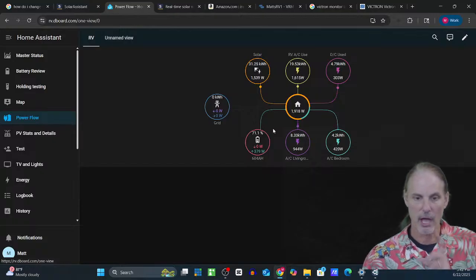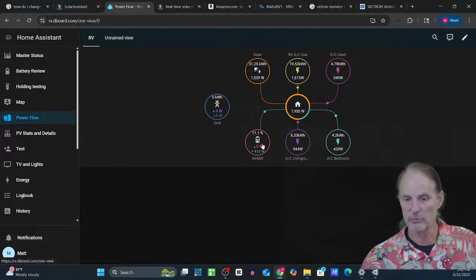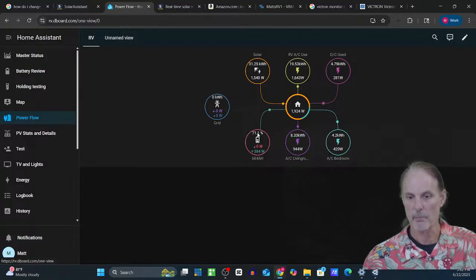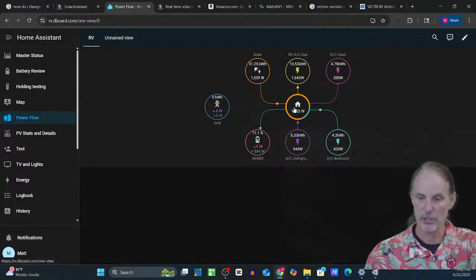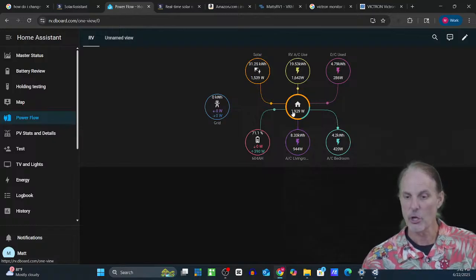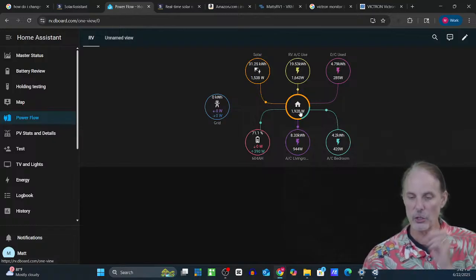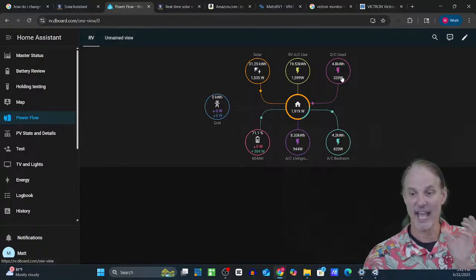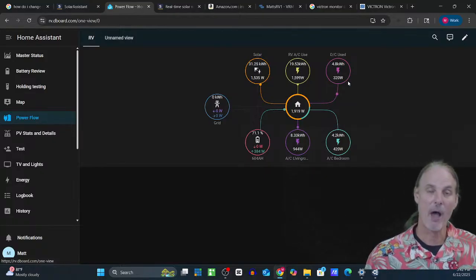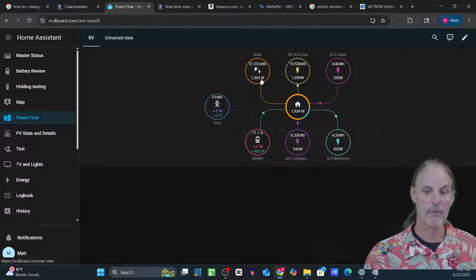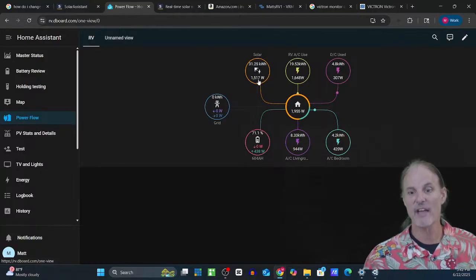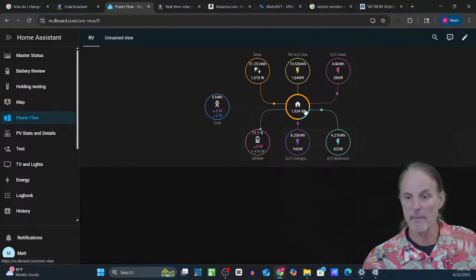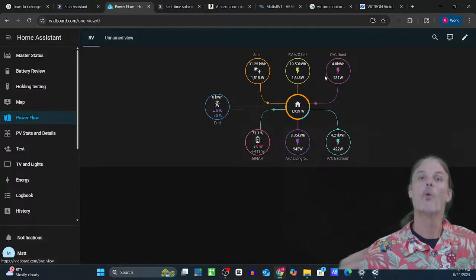The battery is actually on another screen because I didn't have a way to display it here. I was out of space because I wanted to actually see what the wattage was and not necessarily the total. So I put the state of charge there instead, but I can see the battery input on another screen. But this shows me the total wattage being used by the 6000 XP, or the inverter in this case. And then from there, I calculate what is the DC power that you didn't account for. If I'm creating 1.347 kilowatts or however many watts that is, and it's feeding this in, and this much is going to the battery, and this much is being used, everything left was consumption.